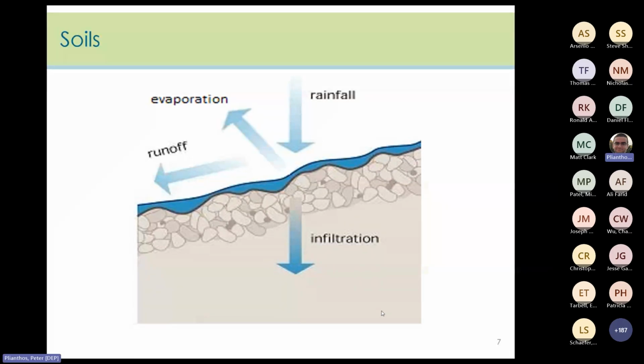When the voids become full of water, the soil becomes saturated. Saturated soils cannot absorb any more water, so there is more runoff. Many of the stormwater practices used on developments are designed based on the assumption the soil is fully saturated, so we can best predict the amount of runoff produced and manage it safely.